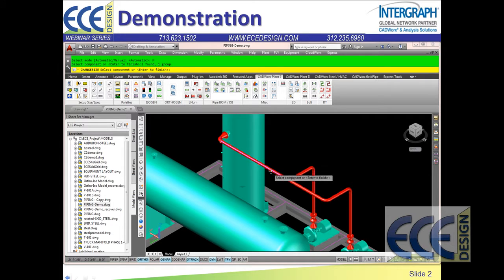So we'll select our elbow, pipe, and T, this pipe, and this elbow. And once you've selected those items, the system will show you a dialog and show you what size those items are and allow you to select what size you want them to be. So I want to go from 4 to 6, and then the system highlights this T and says, hey, that size is not available. We got to change this component.